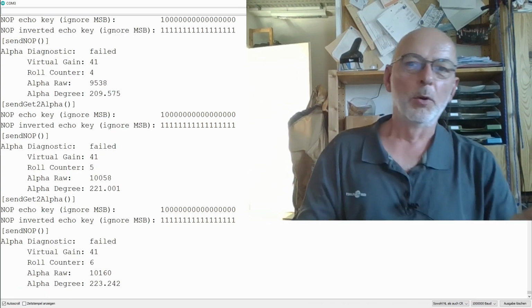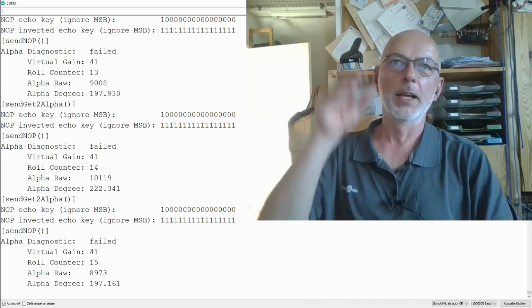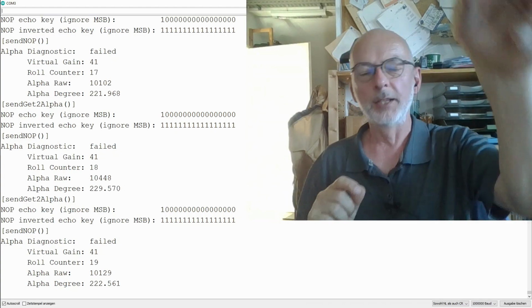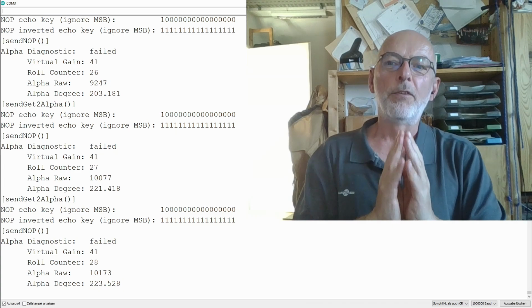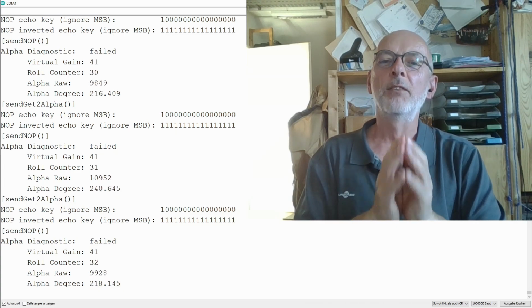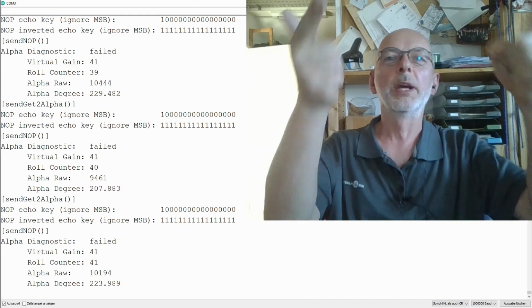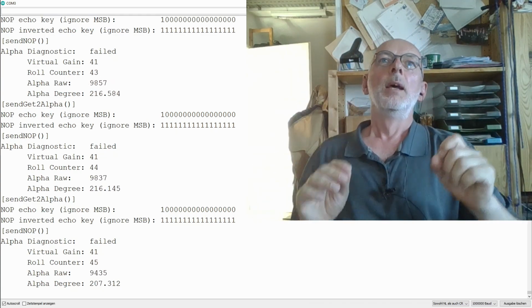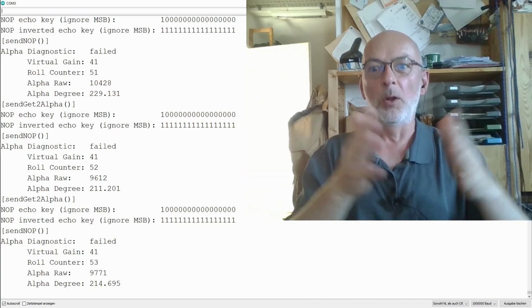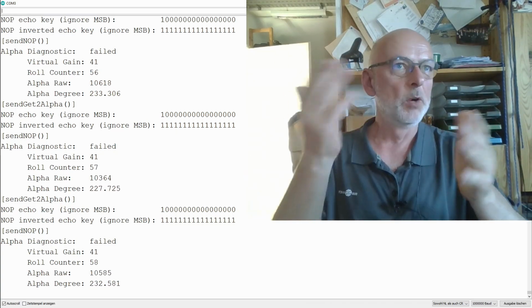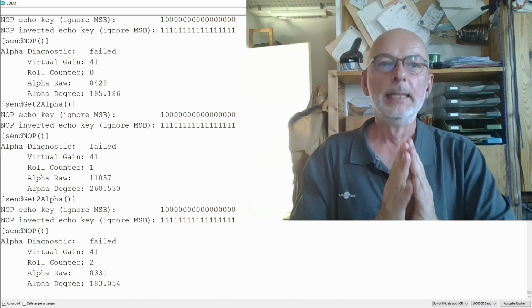So to summarize, usually you would just use trigger mode 1. Send an SPI transaction, get your result back in the next SPI transaction. If you are forced to use a very, very slow SPI bus, then you might switch to trigger mode 3. Keep the frame rate up at almost maximum, even with a 100 kilohertz SPI bus in our example.